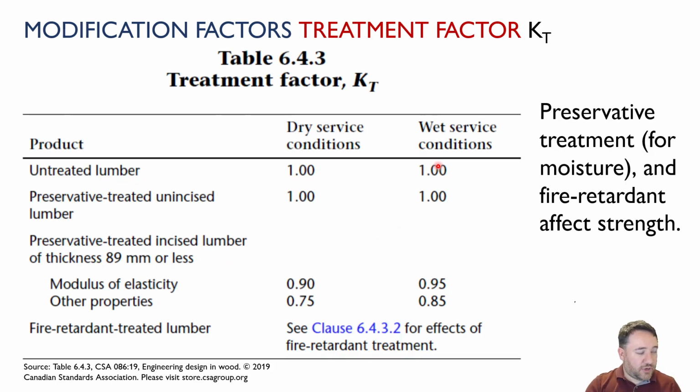Okay, moving on to, I think we're on number 4, right? Modification factor type number 4, which is treatment factor. And this accounts for the fact that sometimes we want to treat wood.